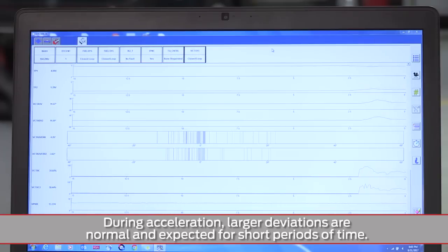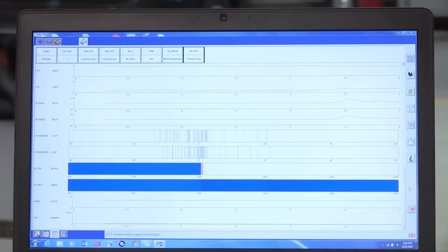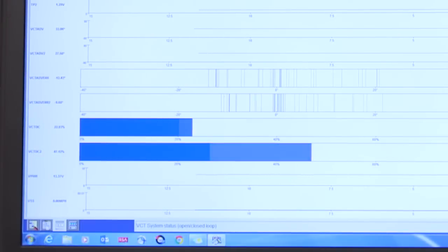Also, it can be helpful to monitor the activity of the percentage of solenoid duty cycle PIDs. Pulse width modulation should be the same for both banks. If there is significant disparity with the response on one bank, the PCM will try to make an adjustment for the affected bank by increasing the duty cycle. You can see that here while monitoring these PIDs using the IDS data logger. Note that some minor variation is considered normal.